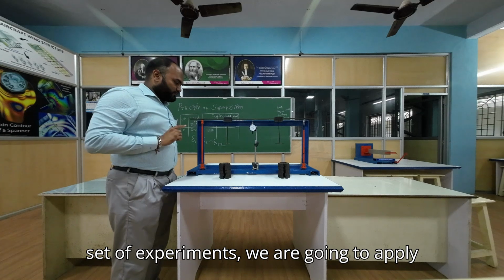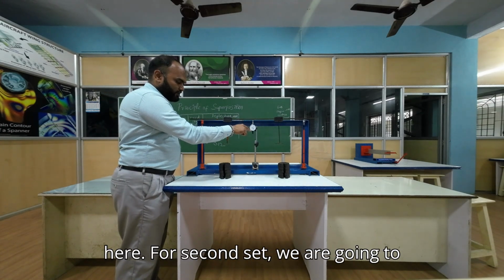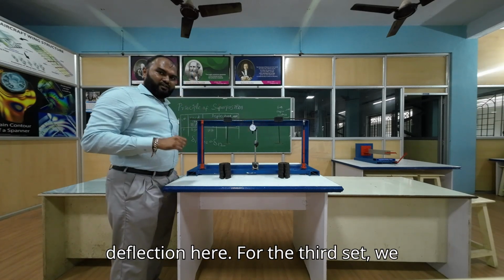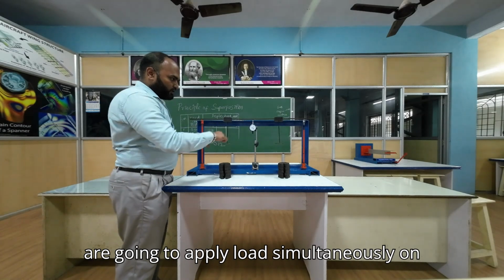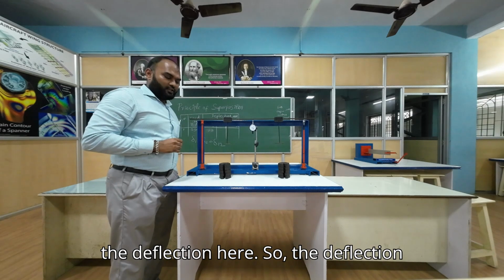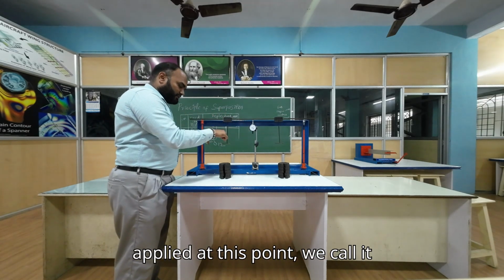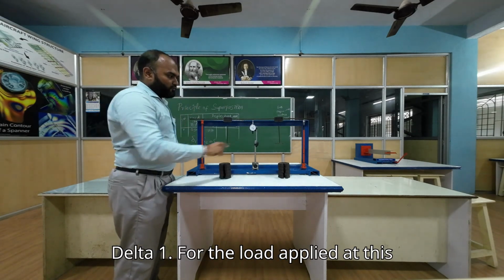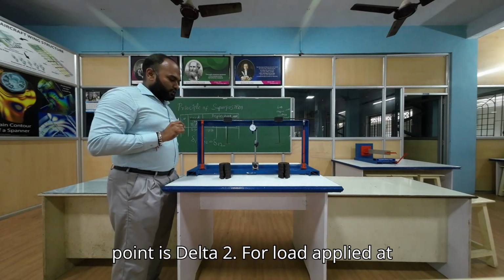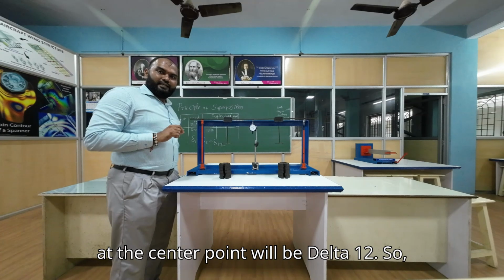For first set of experiments, we are going to apply load here and measure the deflection here. For second set, we are going to apply load here and measure the deflection here. For the third set, we are going to apply load simultaneously on 2 points, and we are going to measure the deflection here. So the deflection measured at this point by the load applied at point 1, we call it delta 1. For the load applied at point 2, the deflection measured is delta 2. For load applied at both points, the deflection measured at the center point will be delta 1, 2.